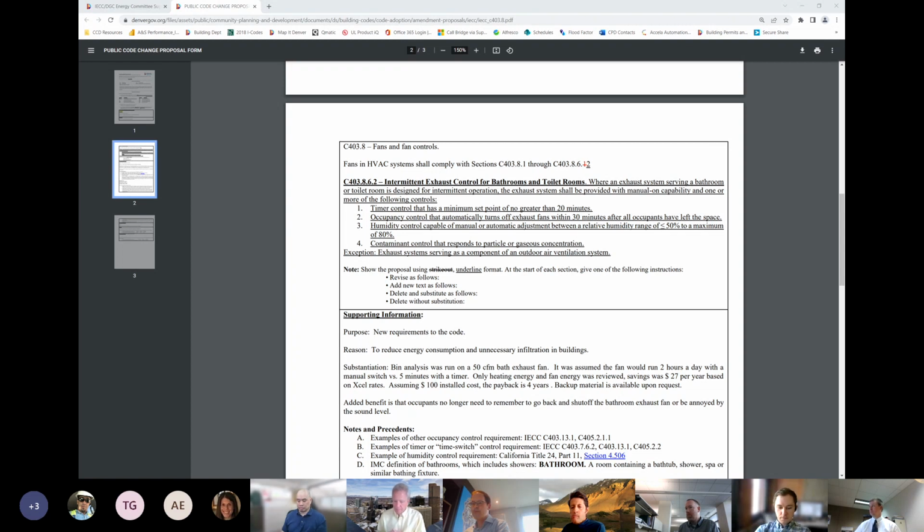It's probably not a lot of residential, at least not the hotels and such, the single family residents, we're going to be forced to have energy recovery systems for the non-transient type of spaces. So the application is the single seat restroom, that sort of thing, in a smaller commercial occupancy. All I'm suggesting is the opportunity to either have a switch or an occupancy sensor. If we leave it as manual on, then you're pretty much forcing a manual fan switch right next to the lighting automatic device.